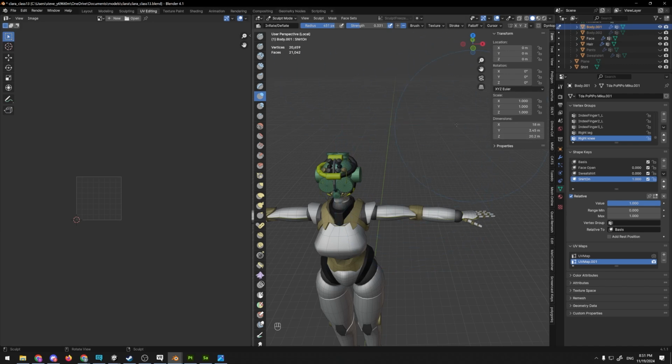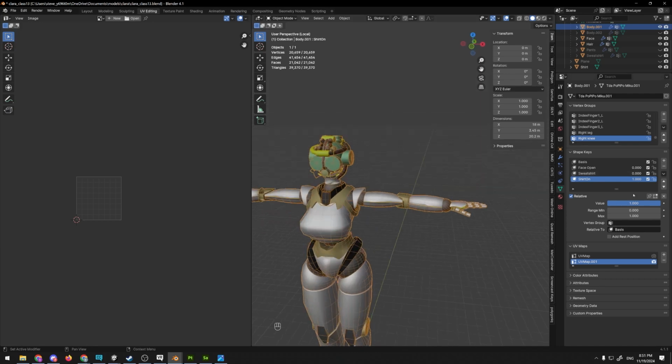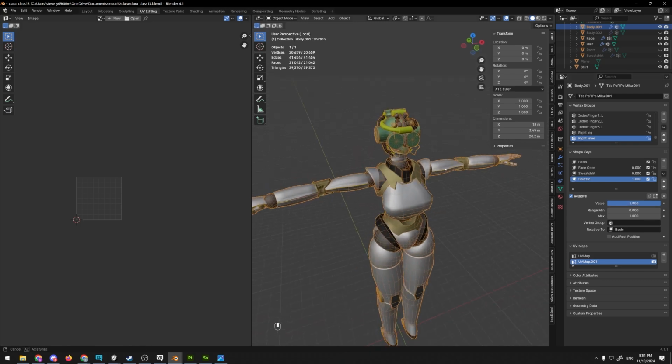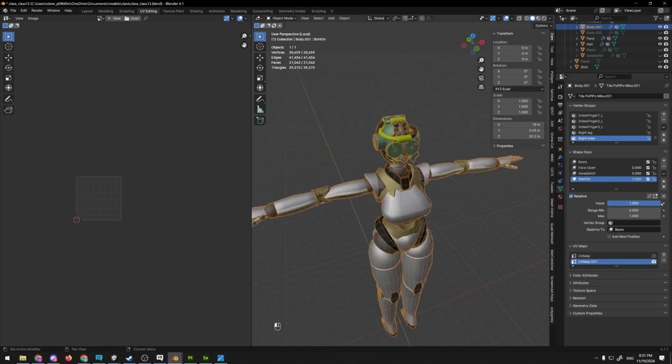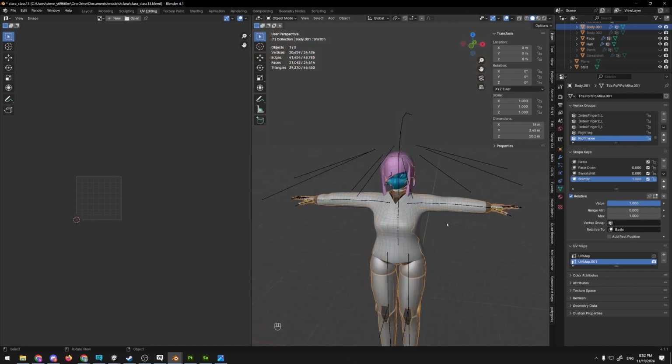And then you can toggle this blend shape on and off. So if I go back in object mode, I can shift this shirt on shape key from 0 to 1 to dynamically make that area of the elbow a little bit smaller. So I would dynamically turn this on while the shirt is on to avoid any clipping that might occur in the elbow. Just a nice little trick that can be used.